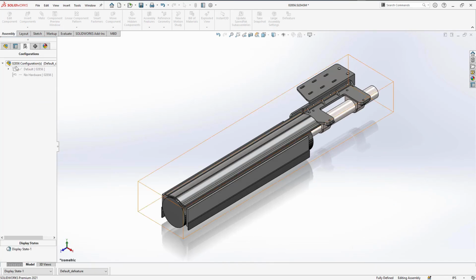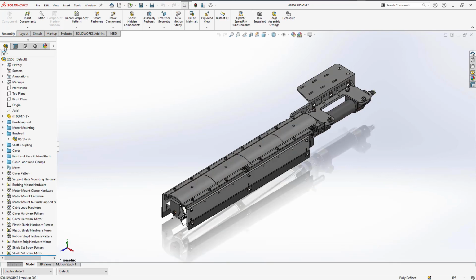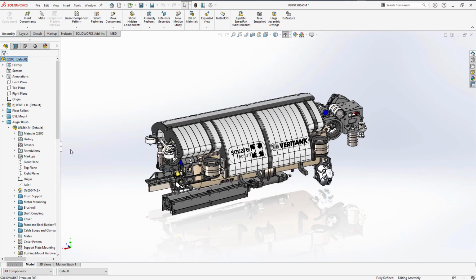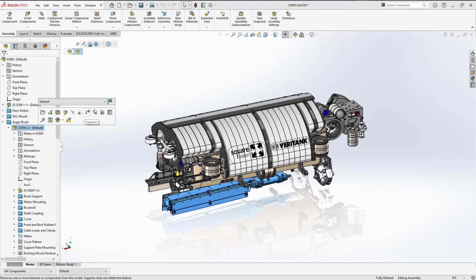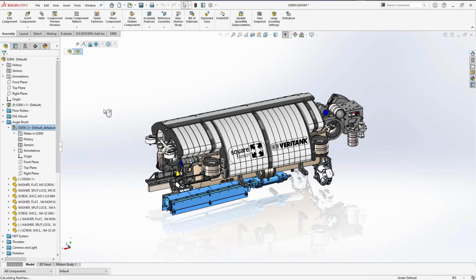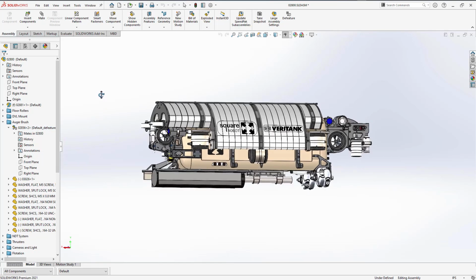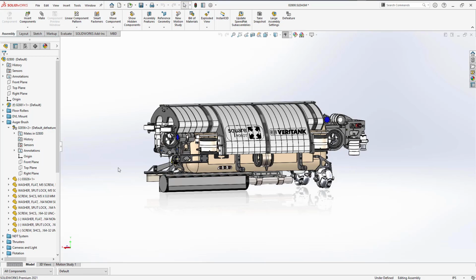You may still want to use those other methods when using Silhouette Defeature to remove proprietary information from a design to share outside of your organization as a separate disconnected file. However, when using the defeatured models within a higher level assembly, you can simply choose a new configuration from the configuration drop-down menu. Defeatured assemblies as configurations provide a way to both simplify complex assemblies visually and also add a performance boost in cases where all of the details of the individual components aren't necessary.